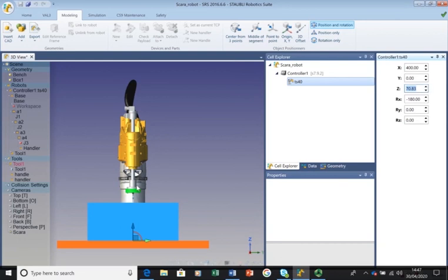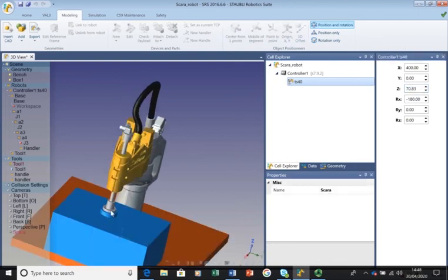Right. At this moment in time, this robot has come into the room. Imagine buying it off the shelf, and it knows where the end of the robot is. The end of this flange is where it thinks the tool center point is. But we've just put a 25mm flange on there. So the tool center point is actually 25mm offset, and depending on what type of gripper you put in, all of that matters, especially if you go into predefined locations and stuff like that.